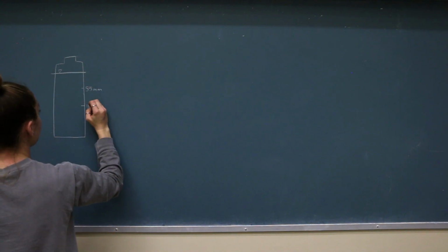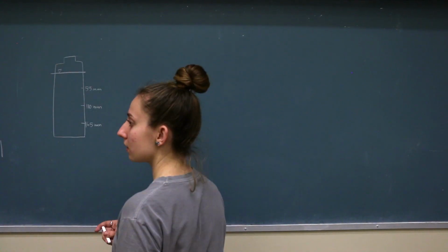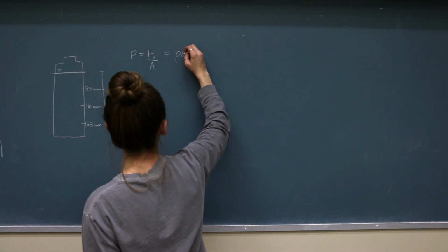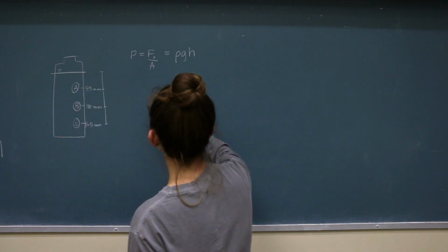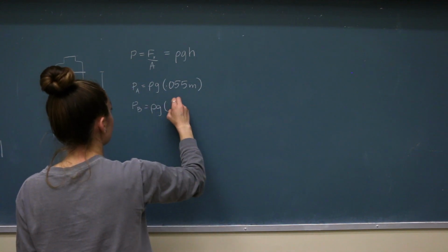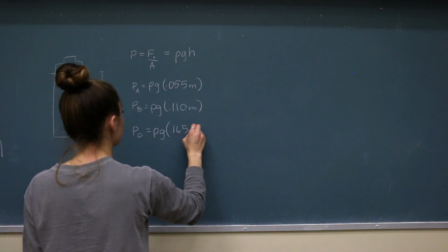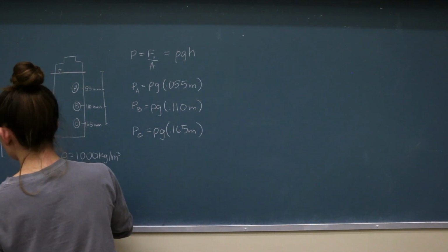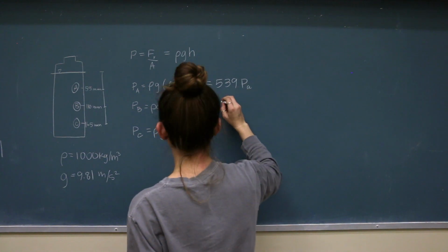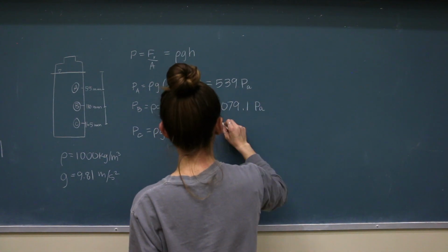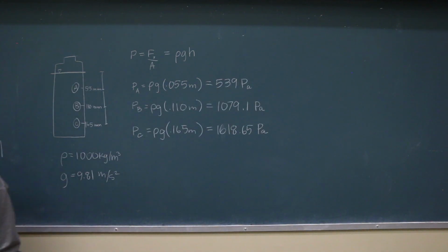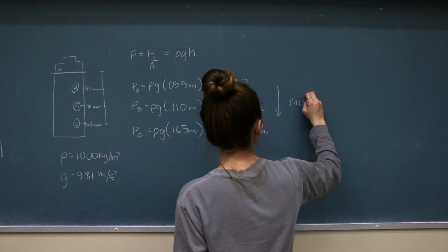As an overview explanation, hydrostatic pressure is the result of all the weight of the fluid on top of a given point in space. So in our example, the hole that is closer to the top of the water line has less water above it than the lower water holes. Thus, the closer the hole is to the water line, or the smaller h is in our equations, the less volume of water sits atop it, and the lower the hydrostatic pressure. Further, as seen in our initial demonstration, you probably noticed that the top water stream actually stopped. This was due to the hydrostatic pressure becoming too small to overcome the cohesive and adhesive forces.